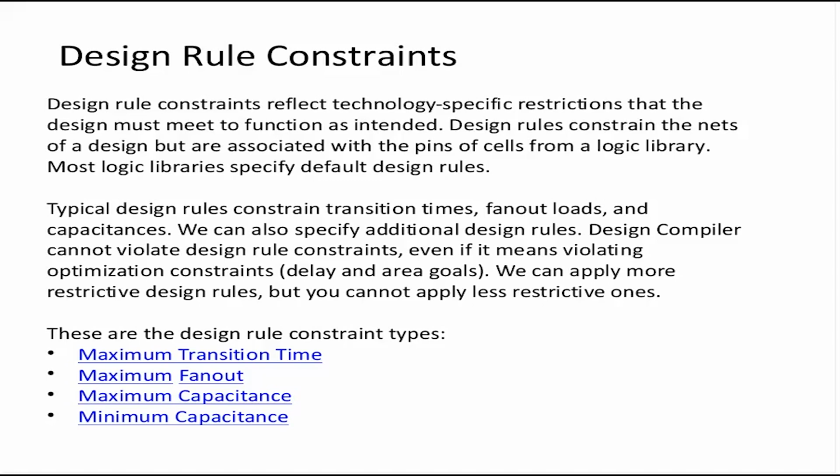One is the inherent cap of the gate output itself. Another is the cap represented by the net it drives, which in the synthesis case will mostly be a wire load model. And third is the fan out, that is how many gates it drives, and the capacitance of all those inputs.